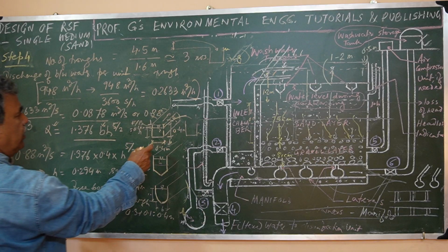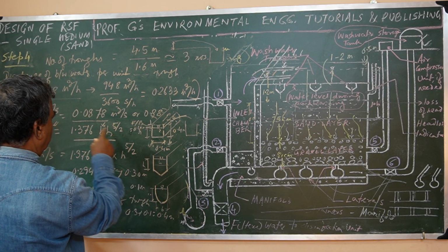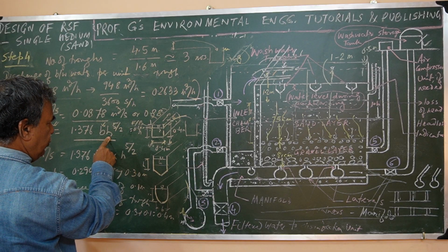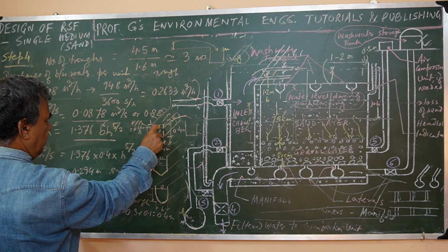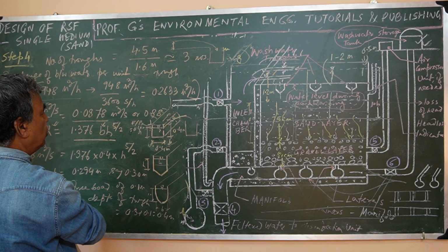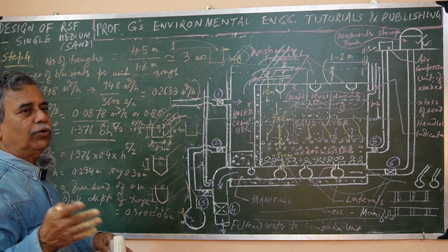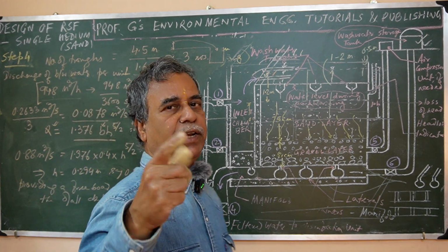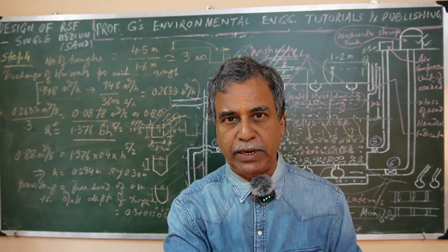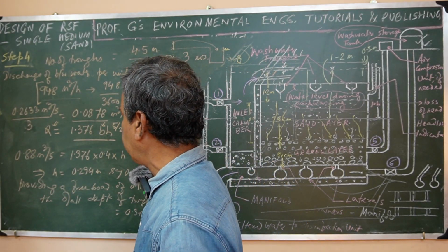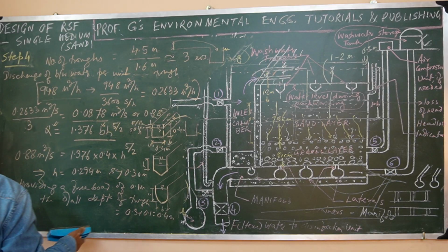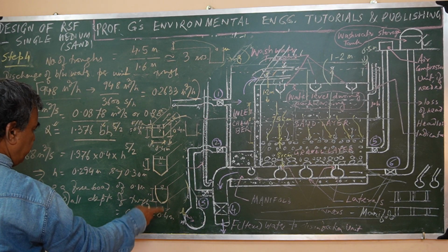Here we have directly assumed, before calculation of finding out the liquid depth also inside the wash water trough, that we have provided 0.4 or so. If you do not get any clue or no experience also, in that case B and H you can take same also initially. Okay, B and H, and accordingly you can calculate this one. So depth is 0.4 meter.